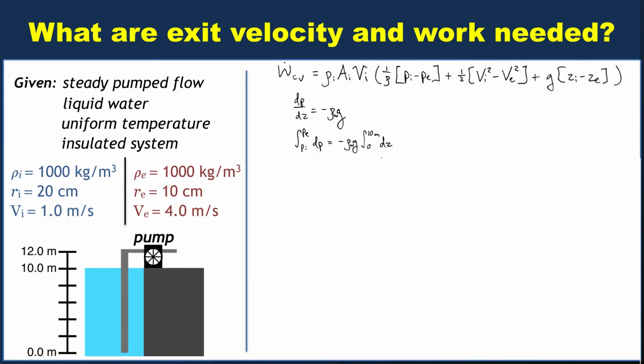My claim is that the density of air is so low compared to that of water that the air pressure difference between 10 meters and 12 meters is negligible. It's basically the same pressure. That's why your ears do pop when you go 10 meters underwater, but if you change an elevation of 2 meters in air, you don't notice anything.